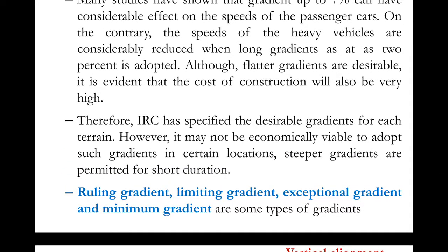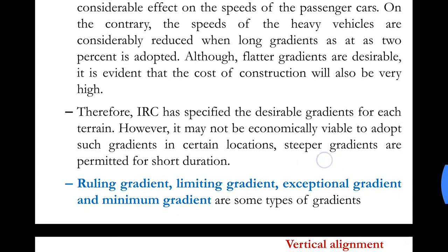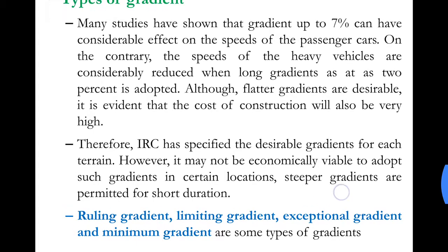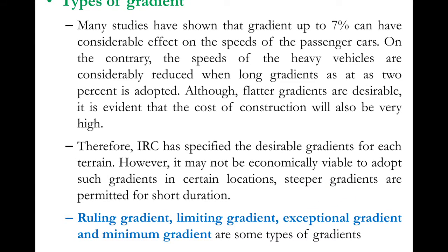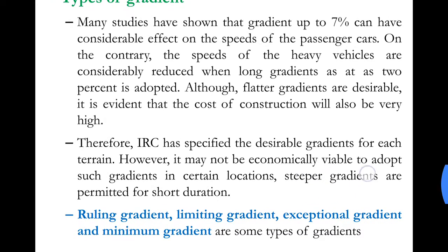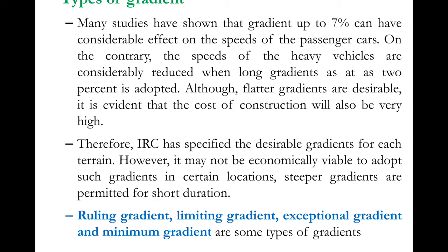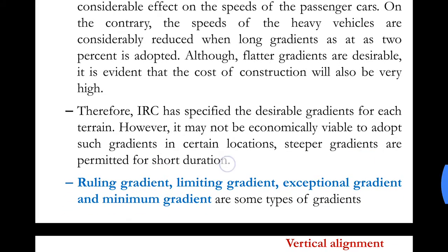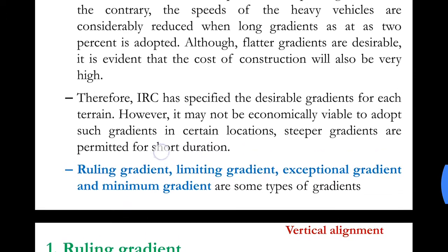So we do not provide these steeper gradients for a longer span or longer length, because these type of gradients require higher haulage capacity, higher load carrying capacity, and vehicle operation cost is more. So we do not provide them for longer durations but for shorter durations.